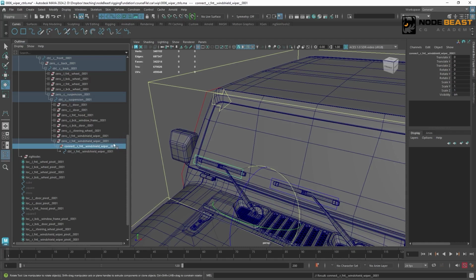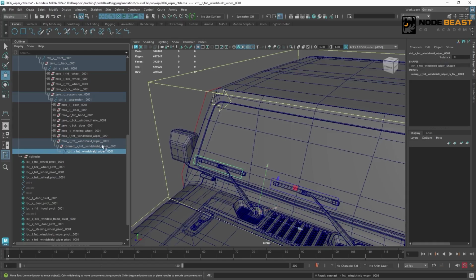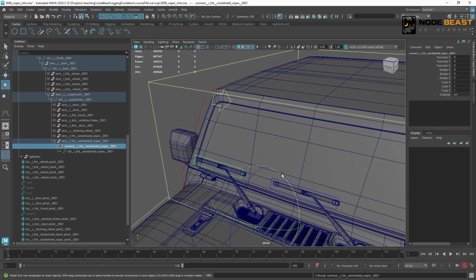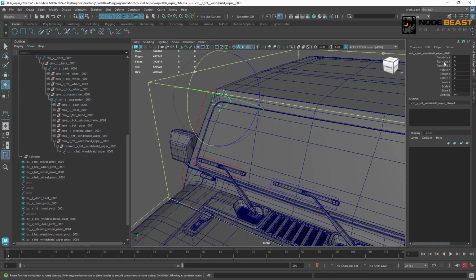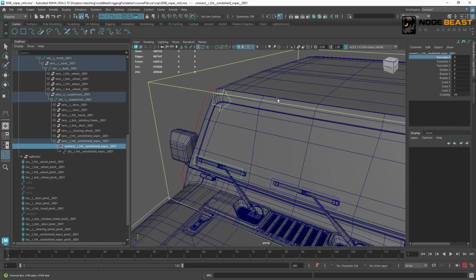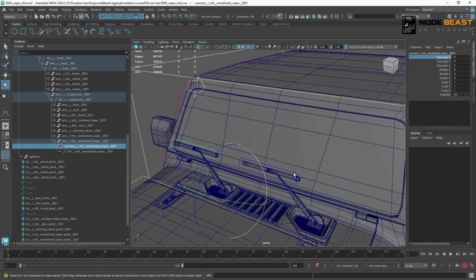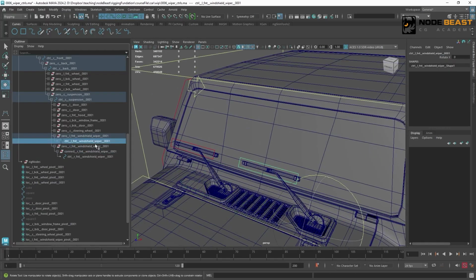This way, look, when I create this group, it is in the same coordinate system as the 0 group. Its translate, rotate, and scale are all at default values, the same as the controller. So if I rotate the x-axis now, we'll see it has a control effect. So we can use the main controller's translate X to connect to the rotate X of this new group we just created to achieve the driving effect. Let's do the same operation for the left controller.